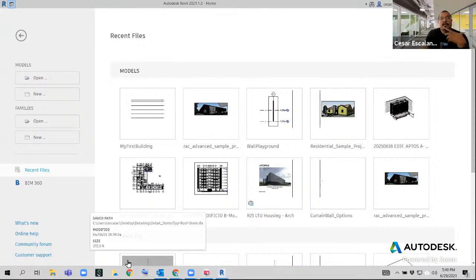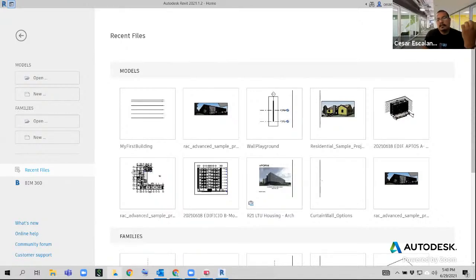And then we associate a layer with a material. I'll show you a little bit of the material library, how we can assign different hatches to projection and cut conditions. And then I needed to associate a thickness, and indicate whether the layer was part of a core or not.